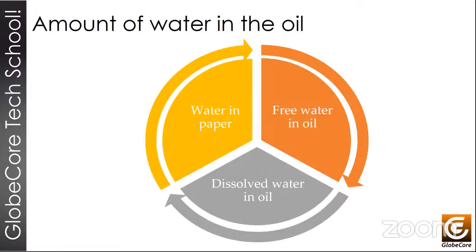Water in the transformer is one of the elements that must be kept track of, monitored. However, it's one of the most difficult characteristics to control. There are several processes by which a transformer will generate moisture, and there are various parameters that all relate to moisture and will affect our attempts to keep the transformer dry.